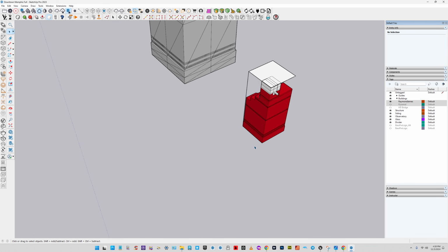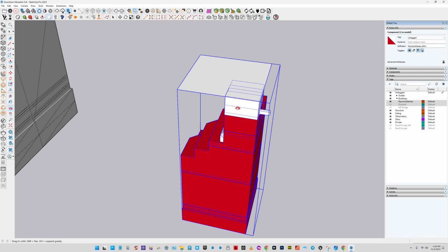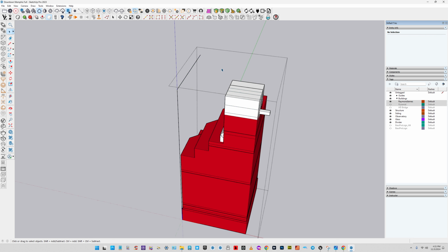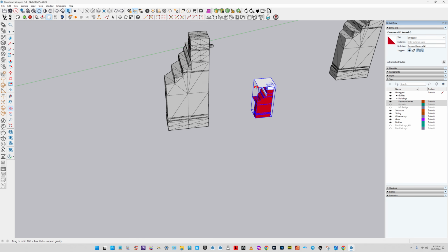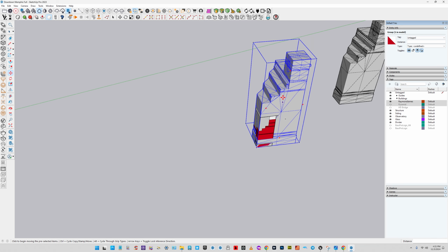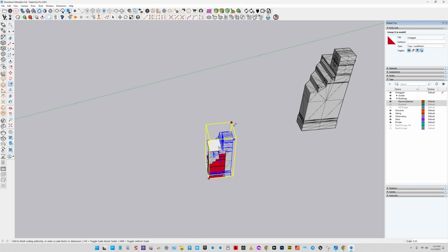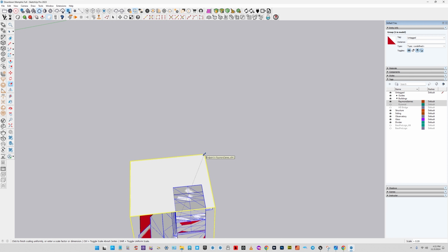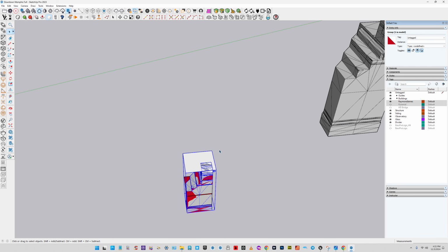Alright, and that should give me the top of, oh, close. Forgot that part. Let's draw a line back from the red axis to this edge, then to this edge, back to there. Okay, so there we go. Now I should be able to move this into place and then scale it right up on this, and it should tell me approximately 0.39. So that's not helpful, because I wish SketchUp would give me the exact dimensions, but this is fine. This will work.